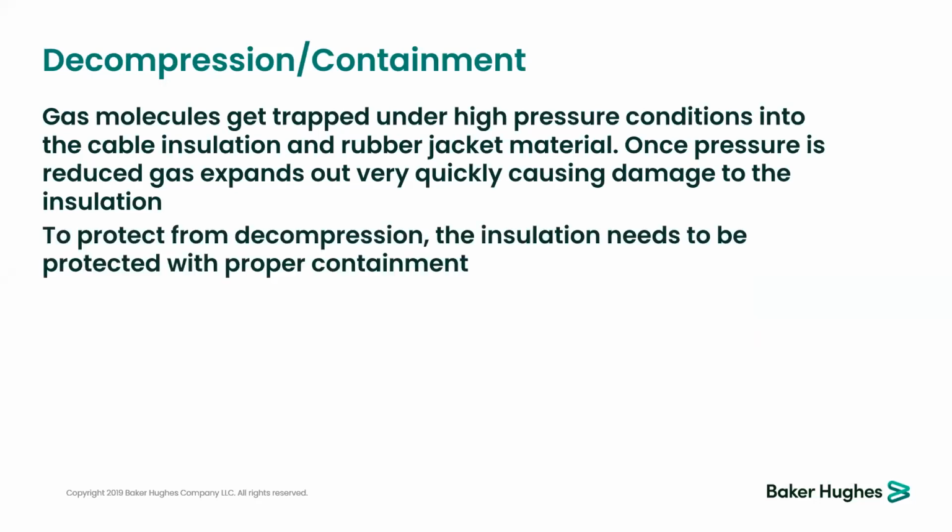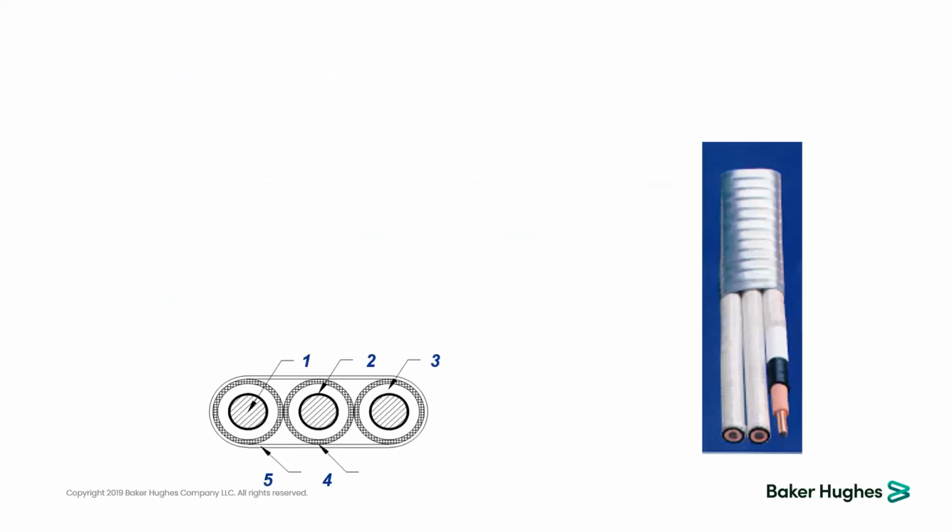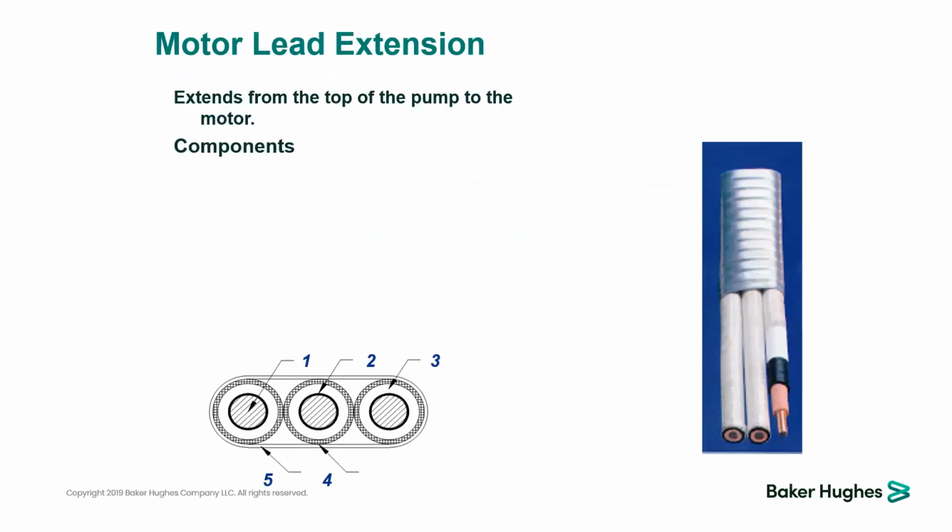Well, this is quickly one of the issues on the cable itself that might affect the cable, called decompression. That phenomenon happens during gas venting from the annulus to the surface. If you are pulling your gas very fast from the annulus, you might affect the integrity of the jacket, and that might cause a crack on the jacket. It shouldn't be covered in this training, because the decompression phenomenon is more extensive.